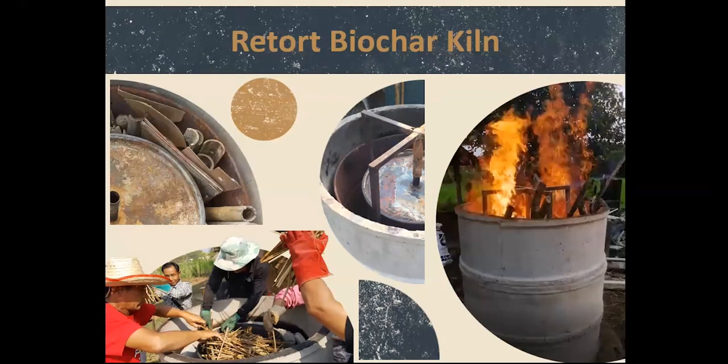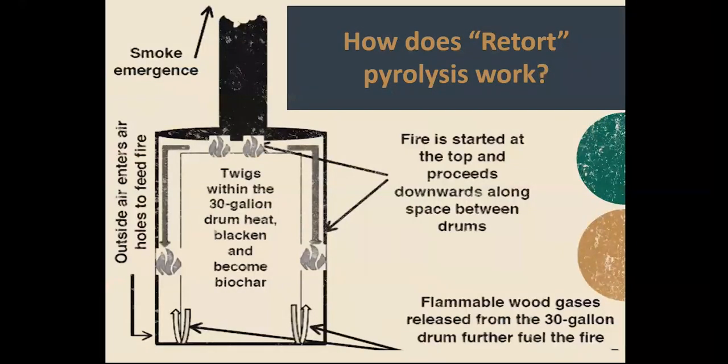And so the biomass inside of this barrel is not contacting flame at all, and it is being heated up in a completely oxygen free environment. And again, we use the TLUD method, top lit updraft, and then the chimney helps create a draft and get a really, really high heat.